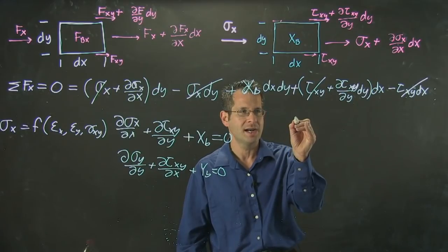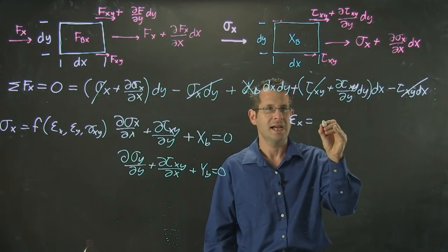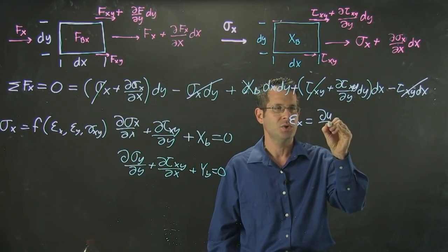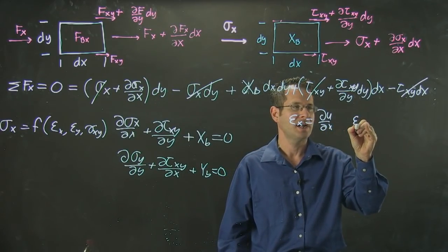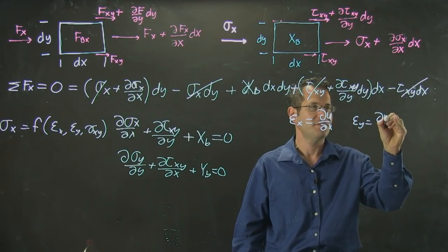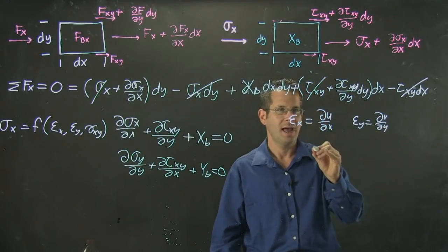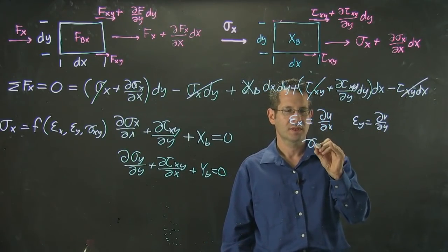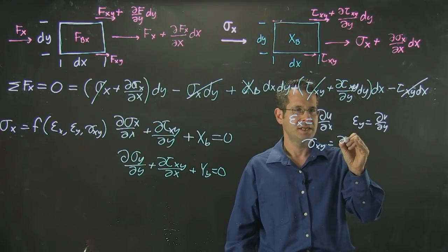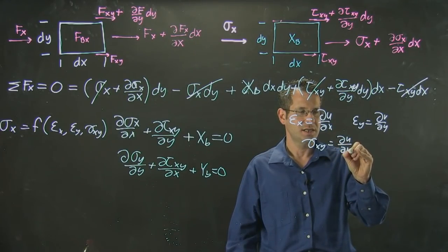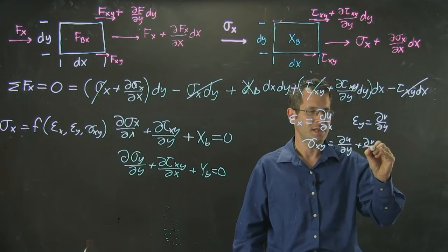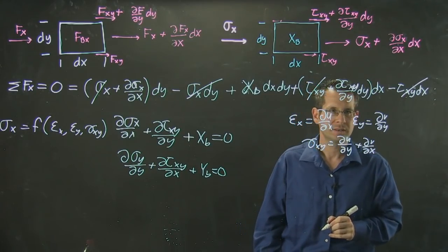And then I can remind myself that strain in the x direction is just du dx. Strain in the y direction is dv dy. And shear strain xy is du dy plus dv dx.